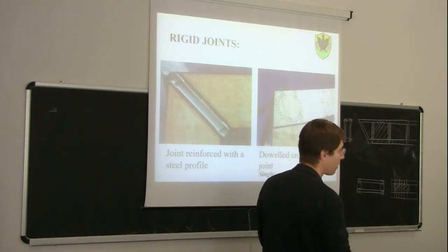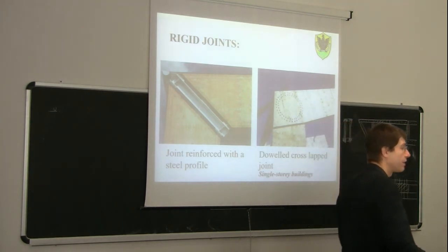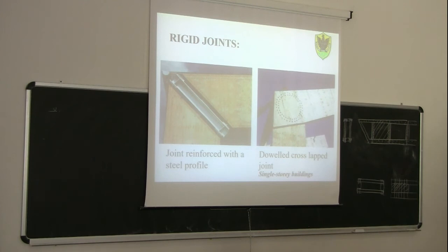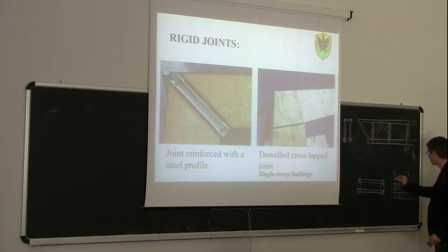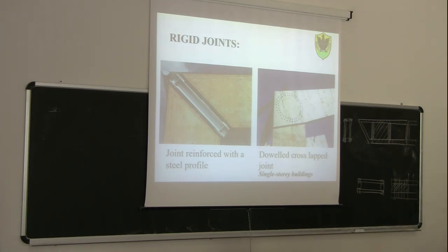If you remember, one problem of the dowel connection is the dowel is just a cylinder of steel. It is tight fitted into the wood, but it doesn't have a withdrawal resistance. So it means that if you only use dowels, suppose that you have some problem, for example someone is pulling down this side here, this one could come outside with very little horizontal force. In order to prevent this, at least 4 of them must have these plates and act as a bolt, in order to ensure that they have some withdrawal resistance.